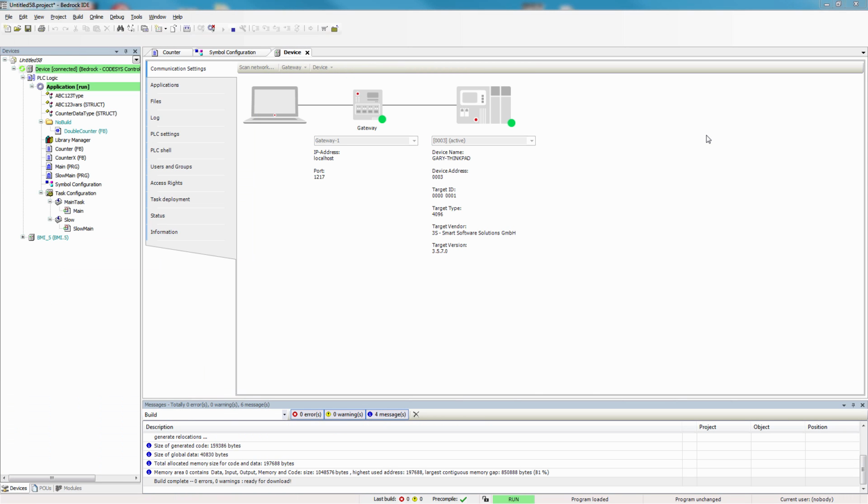Next, let's talk about data sharing peer-to-peer between Bedrock controllers. Now, if you have Bedrock controllers set up as remote I/O, daisy-chained up to 10 Bedrock controllers and SRCs, those variables all just appear flat on the top level. You can't tell that they're not local to your backplane. So that's not what we're talking about here. We're talking about a system where you have two or more Bedrock controllers peer-to-peer. You could have hundreds, whatever, but they're set up peer-to-peer, not daisy-chained in a remote I/O using the SRCs.